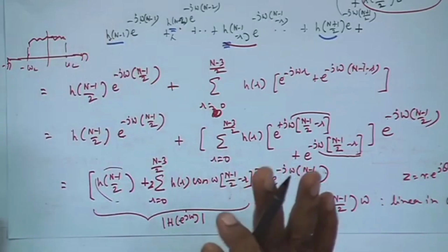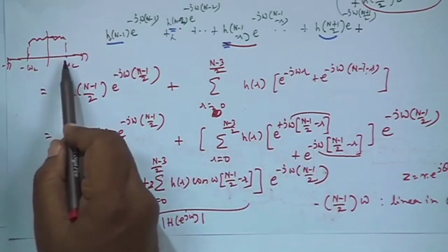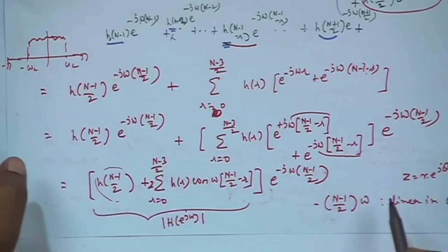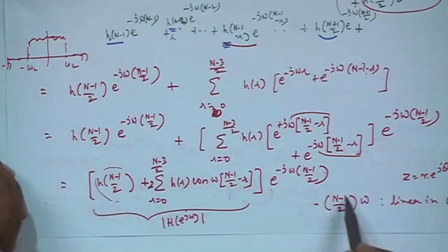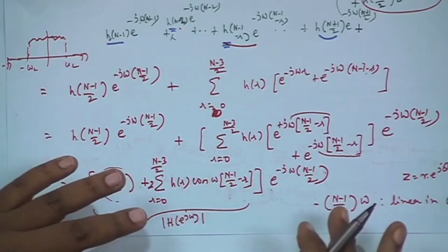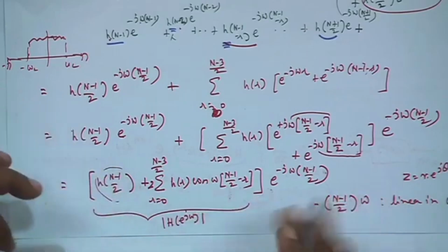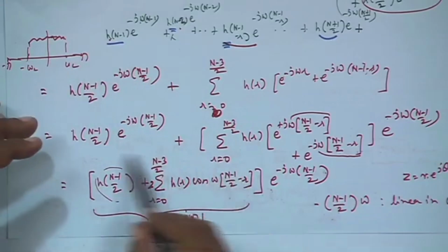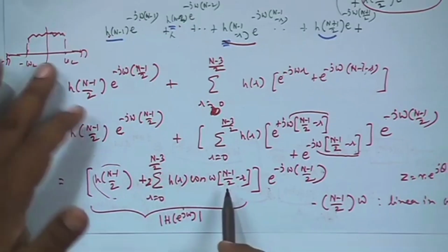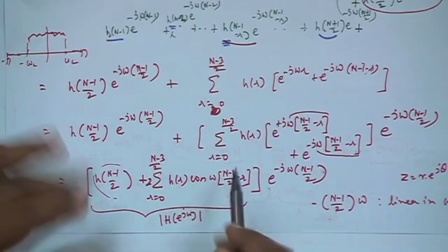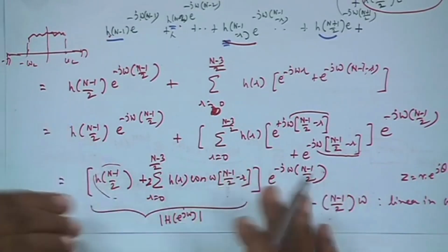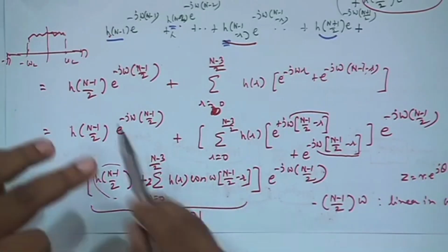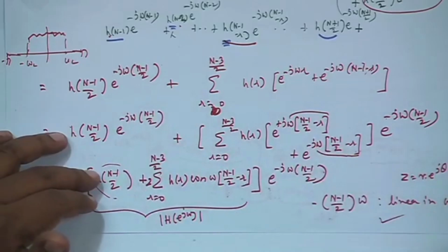It is not undergoing any sign change within the pass band. So, if a band limited signal confined to this band is passed through the filter, there will be no phase distortion, it will only be delayed by (n minus 1)/2, that much delay, okay. And magnitude response also will not undergo much change, it is a kind of constant. I will design these coefficients such that first this whole thing does not change sign, does not become negative within the pass band of the signal, and also its value remains kind of constant, does not change much, okay. That is part of the design of the magnitude part. So, this is possible with the FIR filter only, and you get a linear phase.